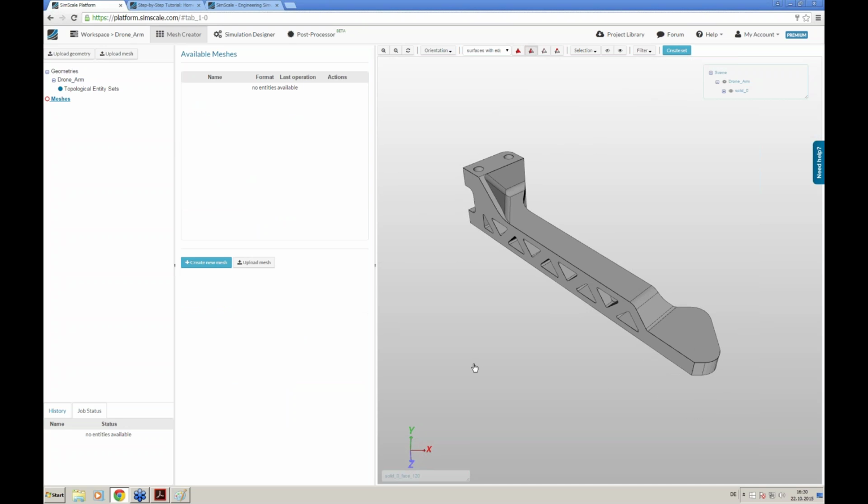You need a mesh because your CAD geometry has a limited number of points, and since the computer is limited by memory, you have to define where exactly you want to calculate the physical quantities. And for sure, more points means a finer mesh.